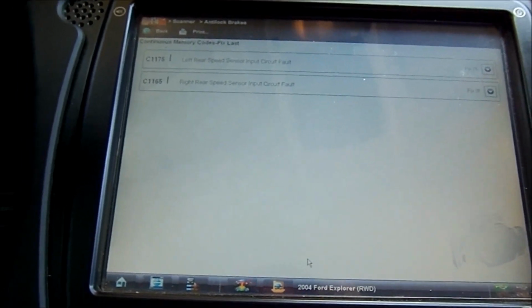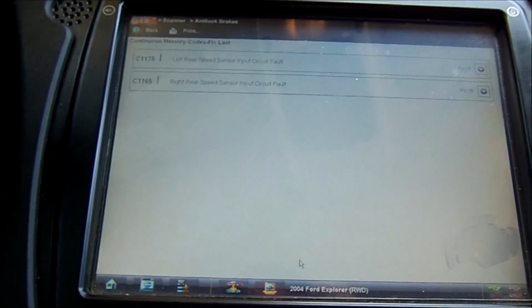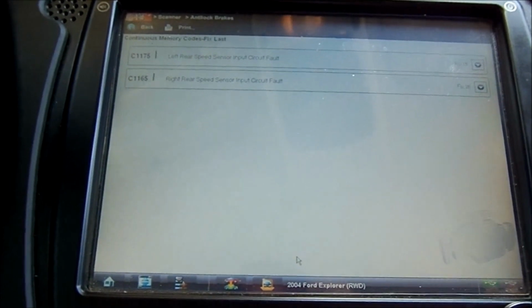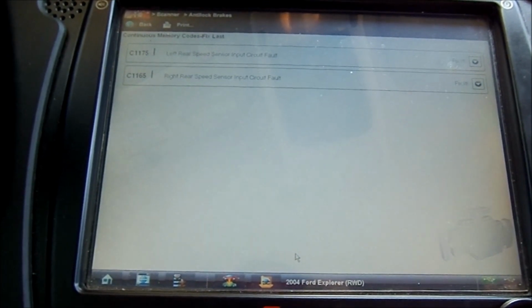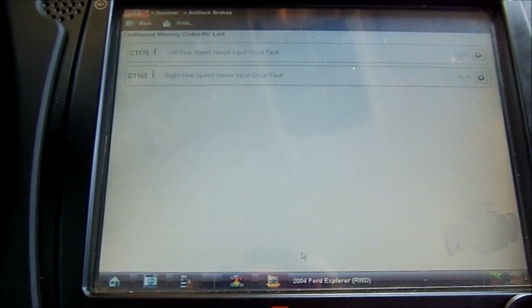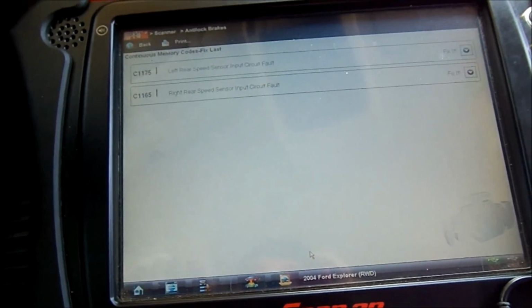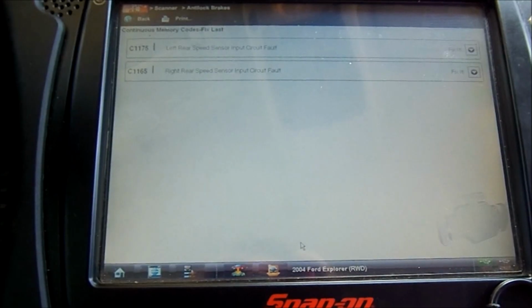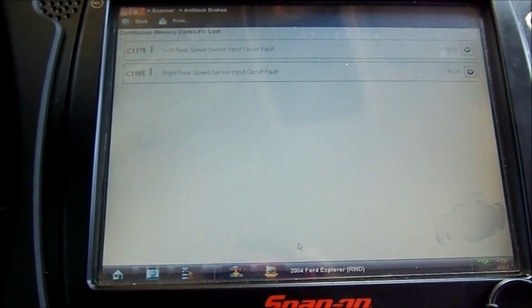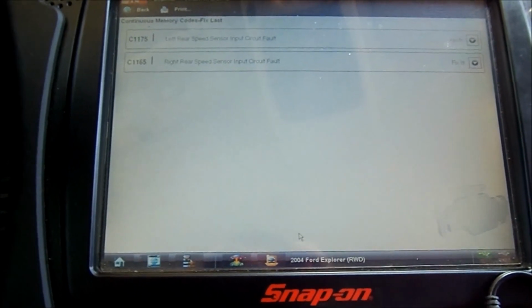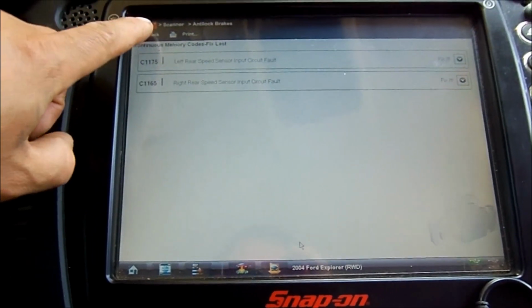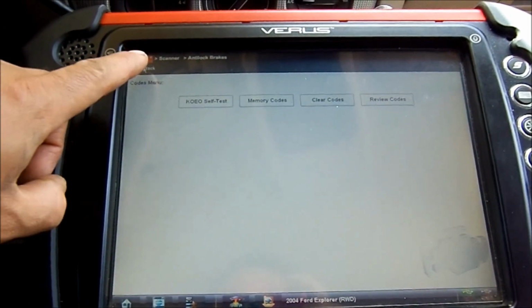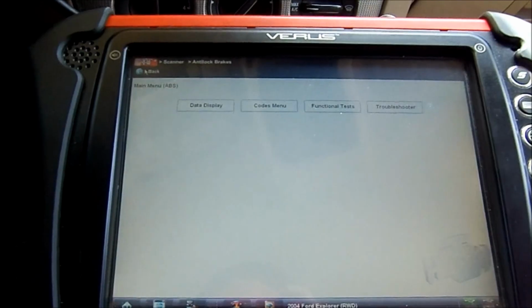Now I was inspecting the vehicle underneath, for my speed sensor connections on the transmission, and they have never been removed. They are connected. This is a 3-channel ABS system, so there is only one sensor in the rear and one sensor for each wheel on the front.